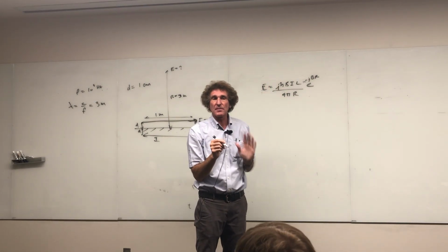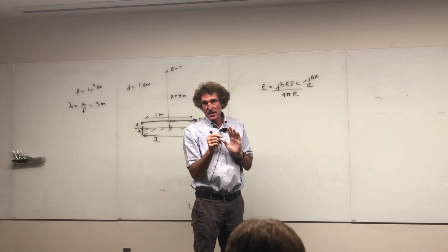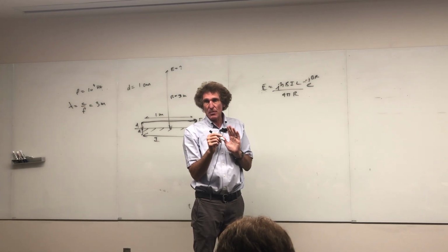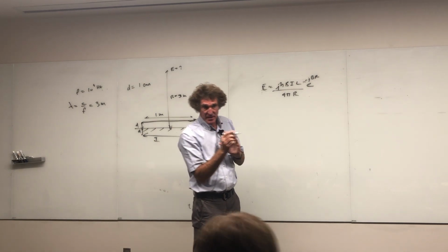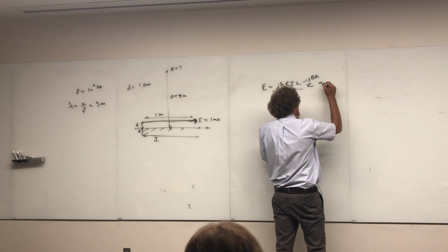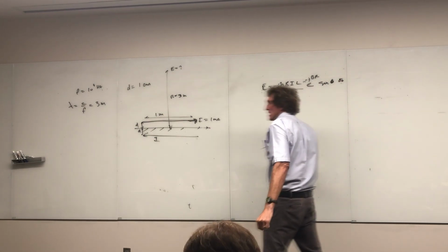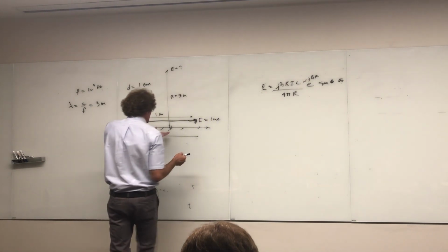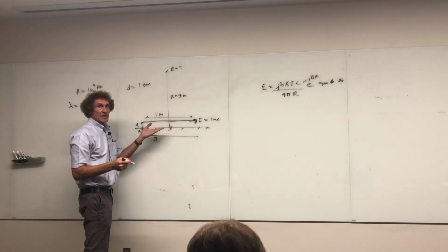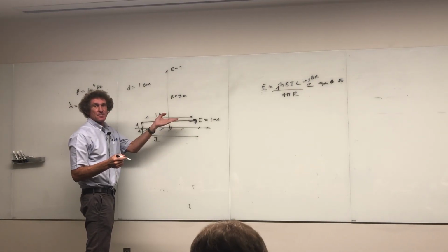Usually we disregard it if you have a single antenna. But if you have more than one antenna, you can't. You have to add them both magnitude and phase together because this is like adding complex numbers. Then there's the sine of theta. And that would be a theta. Now, this one already has the actual observation point perpendicular to the antenna. Do you all follow me on this, class?